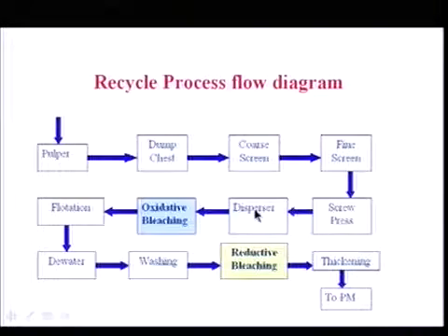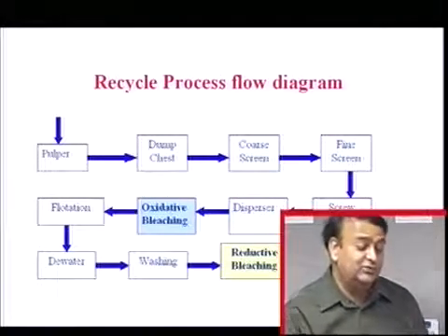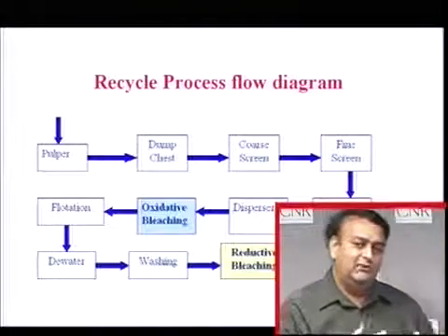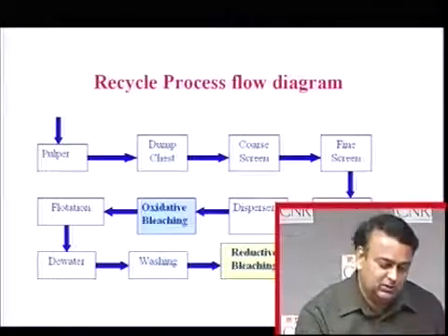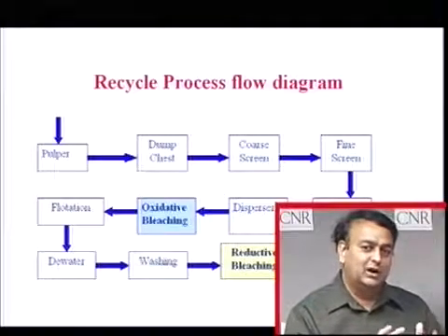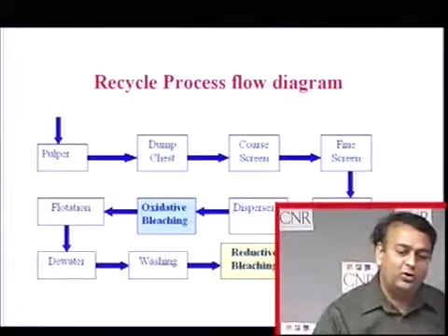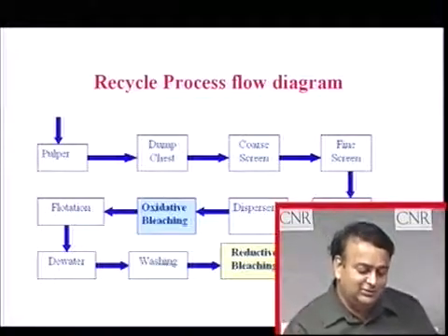In the disperser, the fiber rubbing action works on the ink and breaks the ink particles. So, there is good mixing of fiber, and you need to put energy into it, 3 to 4 horsepower days per ton. When you put energy into it, the fiber gets heated, so high temperature is available. There is good mixing, higher consistency, high temperature, these are all available. It is ideal for peroxide type bleaching. So, you add peroxide chemical in the disperser.